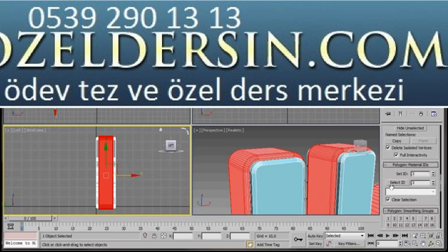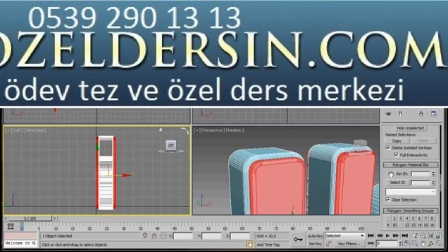Now we can just scroll down to Polygon Material IDs. Set ID, we'll set it to number 1. Press Ctrl I on the keyboard. This will invert our polygons. And now this section we can set as 2.